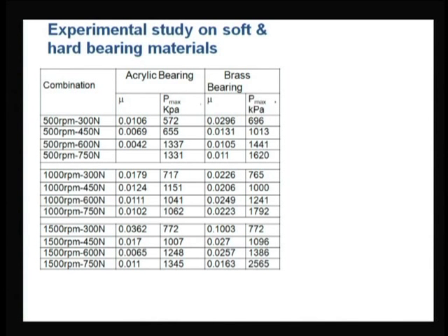So, the interesting thing is that material properties play an important role in finding out what the maximum pressure will be. This is good to learn from a mechanical engineering point of view. Many times in mechanical engineering we design a component and subsequently select the material based on the maximum pressure, without thinking that the maximum pressure itself will be decided by the load or by the material which is getting deformed. Or we generally avoid the deformation and then calculate the maximum pressure, while in reality, in a practical situation, deformation will change the maximum pressure value.